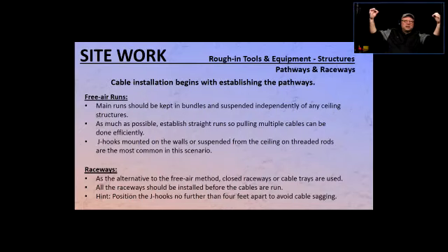When you establish that straight run, you tie a string on one end, and this is going to be a reference guide for mounting the raceway. If it's J hooks, that works great, because you just install the J hooks right along that line, and then you have a nice and straight line. Then you can use that string to pull the wires, and you can tie another string to it, so you have the string there and can pull more wires later.